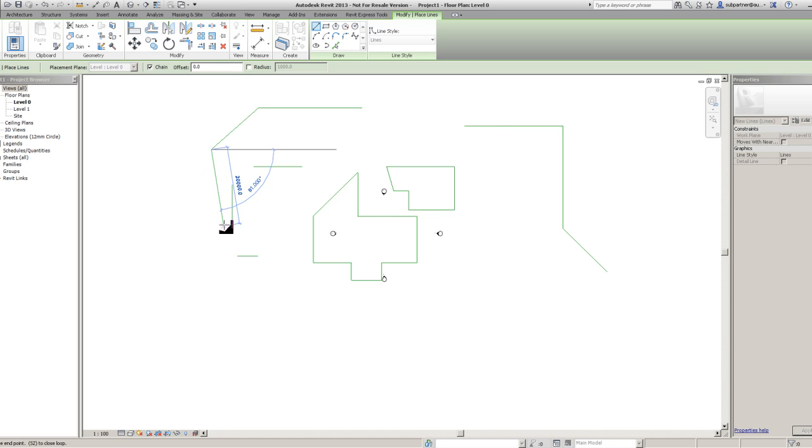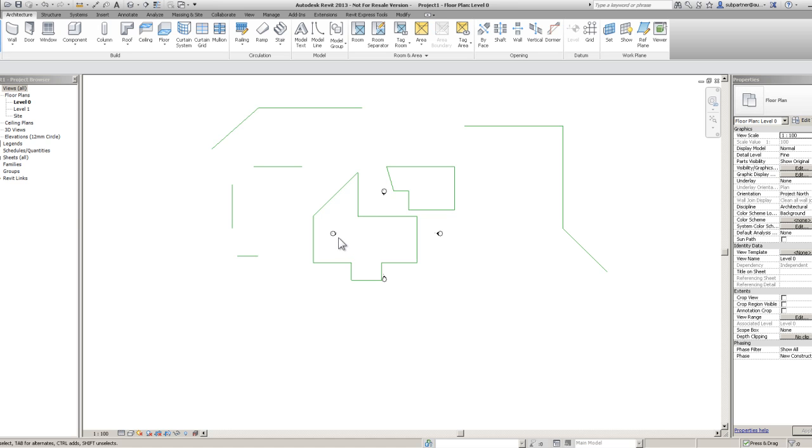I used to go and buy quite expensive mice so that I could program one of the buttons to do escape on the side of it, okay? But basically what we have on our screen here, we have this button here. It's called modify, okay? If we hit modify, it will basically just cancel you out of any task that you are doing there and then, okay? There's a couple of tasks it won't do, which we'll get onto on later videos, but most actual tasks that you do, hitting modify is just the same as pressing escape in AutoCAD, okay?